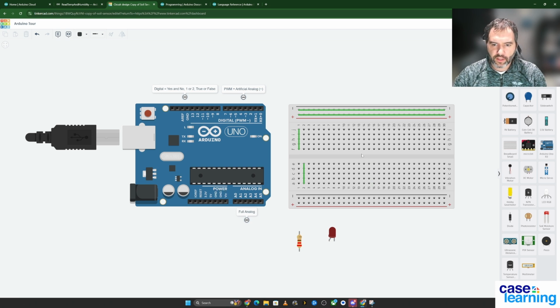On the right side here, we have a breadboard. The breadboard is a very simplified prototyping tool that helps us organize and track all of our wires and connections when making something in a more quick fashion. I drew these green lines here to represent, if you have a ground line, in this case, if I take a wire here, and I'm using Tinkercad to connect these together, a ground line over to the ground portion here. The green lines, those are all the dots that are connected in that circuit so far.